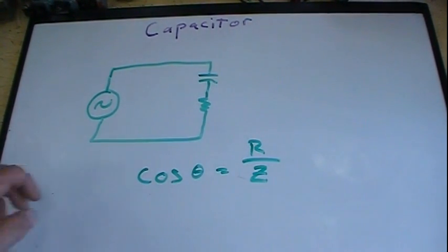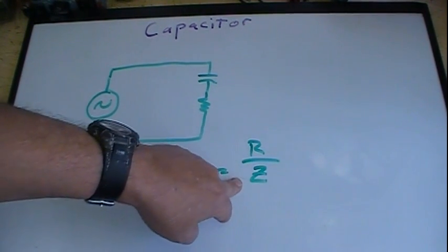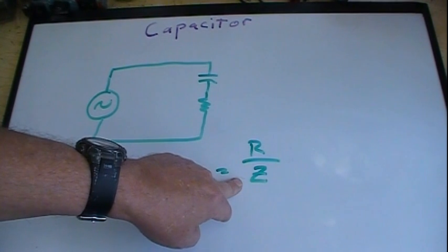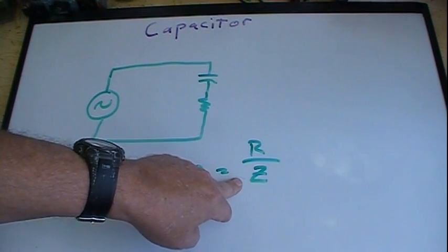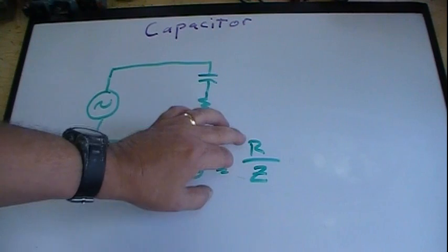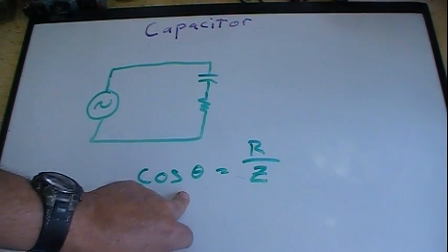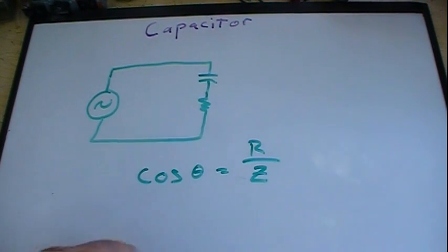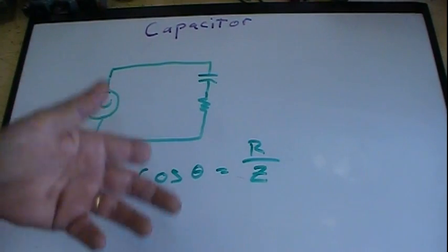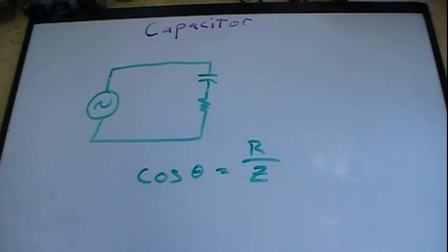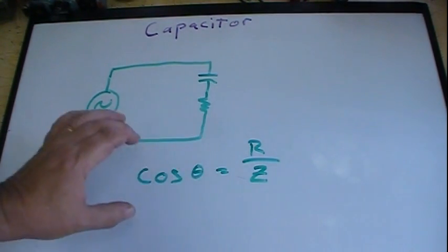Okay, so resistance divided by the impedance of the circuit as it's drawn, numbers like this here. You take this resistance divided by this, gives you the cosine of theta. And you can find then, by using what is known as arc cosine, as just the opposite reversal of the cosine, you can find the angle. So if I take arc cosine of this, I get an angle.